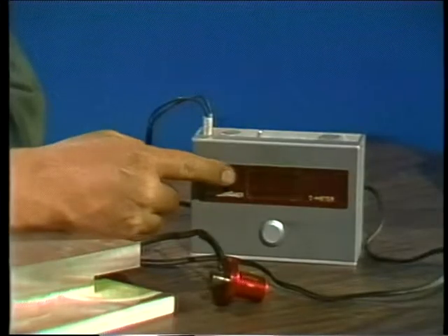Ultrasonic testing is indirect because instead of a defect showing up on the outside of the part, it's seen on a screen like this, or the thickness of the part registers on a digital readout like this. Ultrasonic testing uses sound waves pitched far above the limits of our hearing. A device called a transducer makes the sound waves.